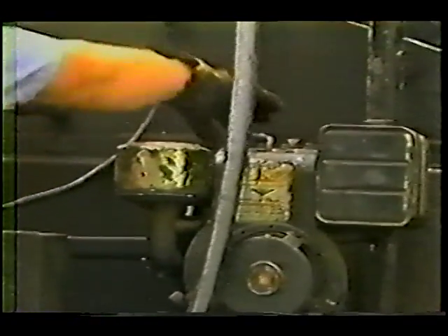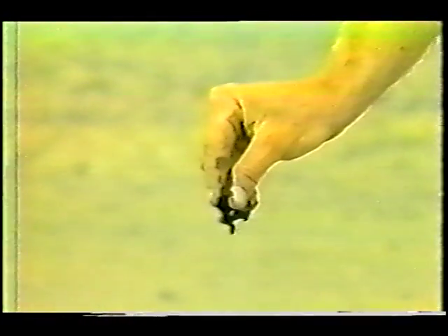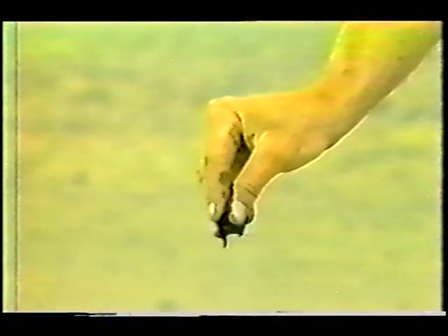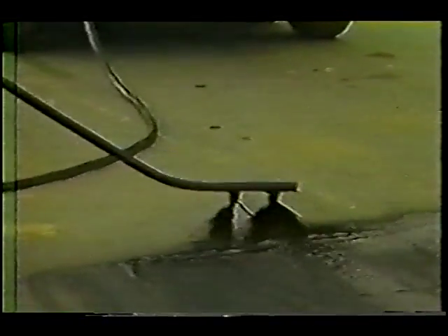Step 4. Apply the liquid asphalt over the cracked area. Before you begin, make sure the asphalt mixture in the cracks has cured. The liquid asphalt should be sprayed over the area in a light coat. You can use a wide squeegee if a sprayer is not available. Make sure the light coat extends beyond the cracked area about 30 centimeters, or the distance equal to the length of your foot. This step is not done for linear cracks.